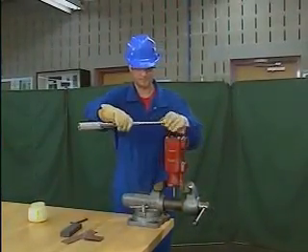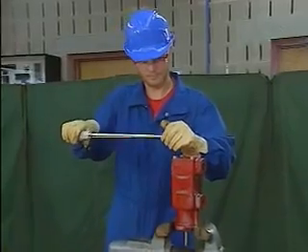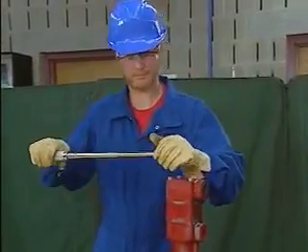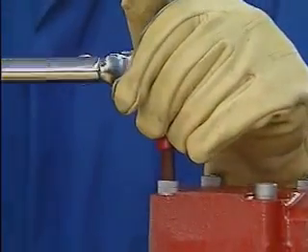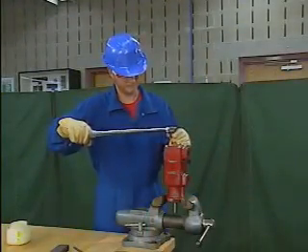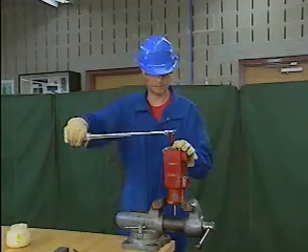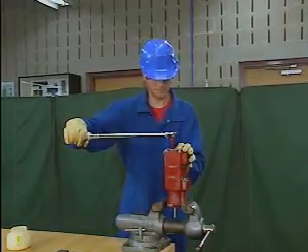Everything looks okay, so the mechanic can install the flange bolts and tighten them in the right order, to the correct torque specifications. When the bolts are properly tightened, the O-ring installation is complete. Now that we've seen the installation of a gasket on a pump and the installation of an O-ring between two pipe flanges, let's try a question on this material.